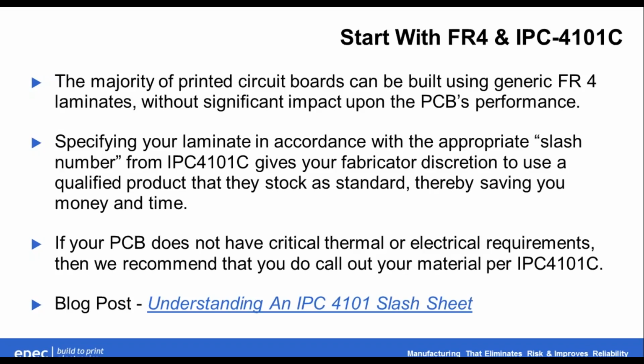If your board doesn't have critical thermal or electrical requirements, we do recommend you call out your material per the spec. And there is a recent blog post by, I believe it was Chris Perry, on understanding an IPC 4101 slash sheet, and that is on our website, and that's the link right there. So if anybody's interested in seeing that, you can check that out.